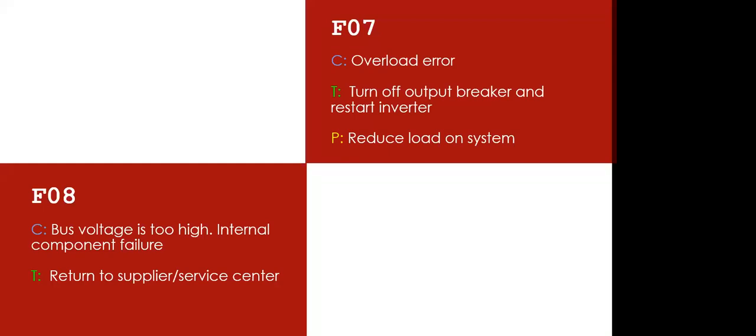What we power on it, we check: is there anything connected that we do not want connected to the inverter? Maybe a socket or a plug, something we did not provide for, we did not have provision to use on the inverter. So we can check through our load and see if there is any additional load on the load we powered with the inverter.